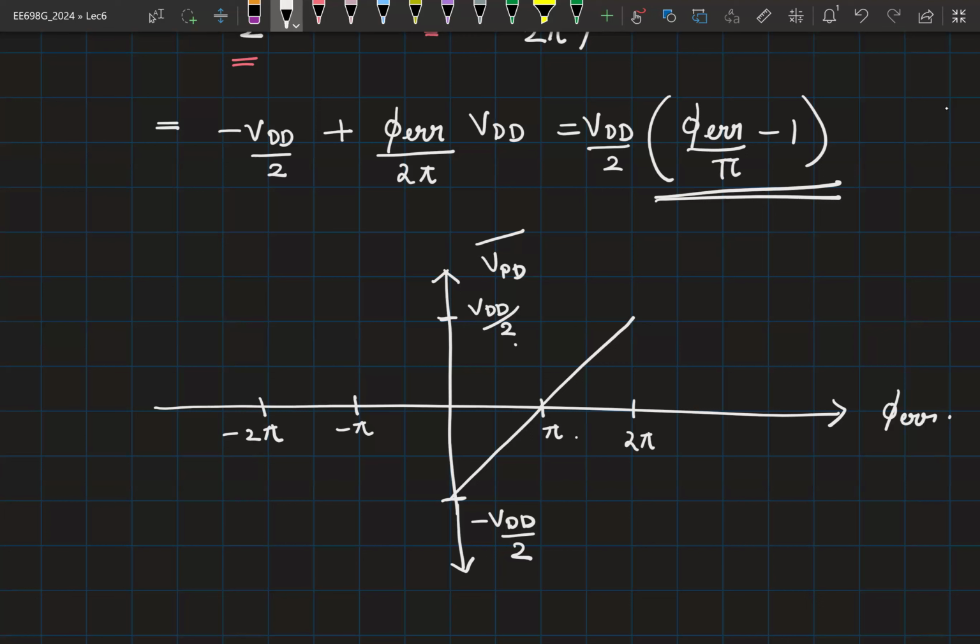Again, if you have a doubt, simply take a sample case, sketch the waveform, and then imagine that waveform being pulled to left or right. So you will see that this is also like this, right? And beyond 2 pi, you would again expect the curve to repeat. Okay. So this way you can sketch the characteristics of a phase detector for any possible input combination of phase error that you choose. Take a phase detector, sketch out maybe for phi error greater than 0, sketch the waveform. Now imagine the waveform being pulled to left, right, and see how your output is going to vary.